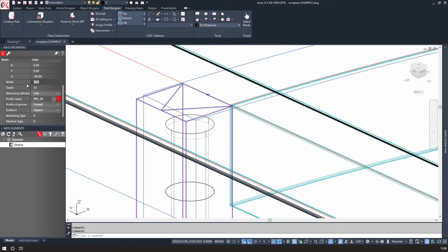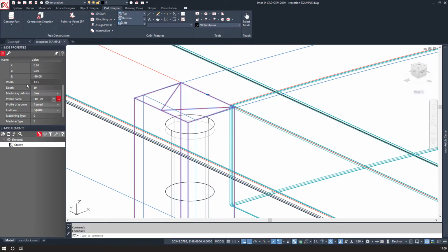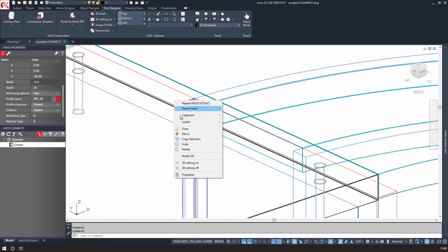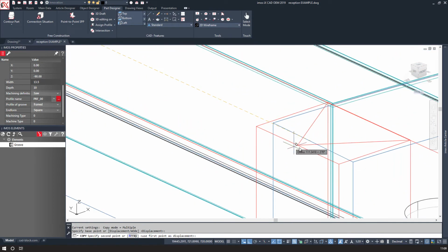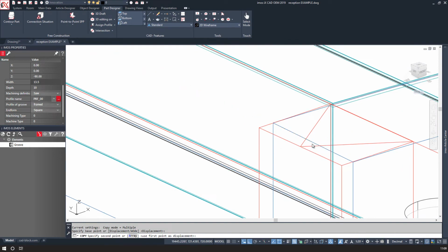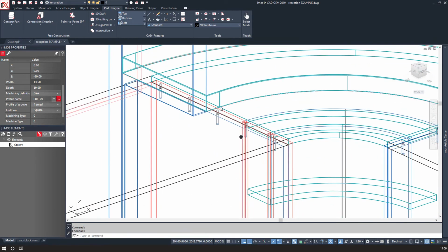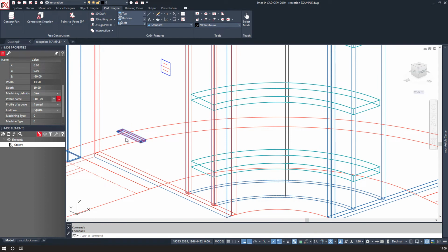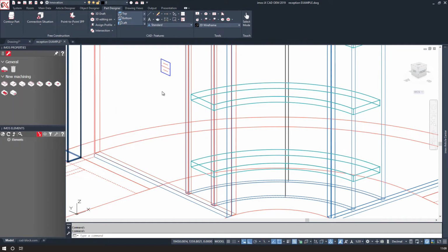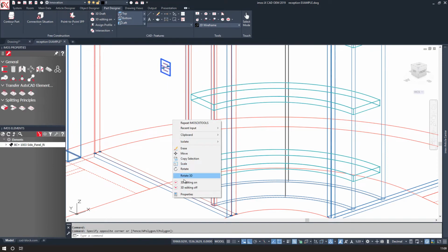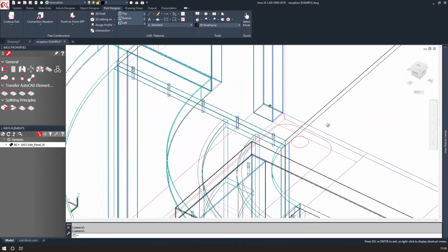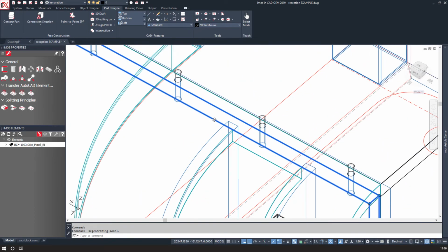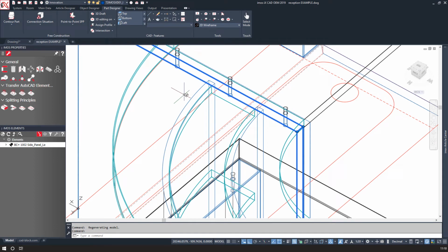Maybe a little bit wider because we need to allow for the laminate as well. This is a bit better, I think. And then I can just copy this and position it again. I need to delete out the other groove as well down here, which I put in by mistake. So I'll just go to the Modify tab and delete. I'll repeat this process for the other side. And then we're nearly ready, I think, to start documenting this.